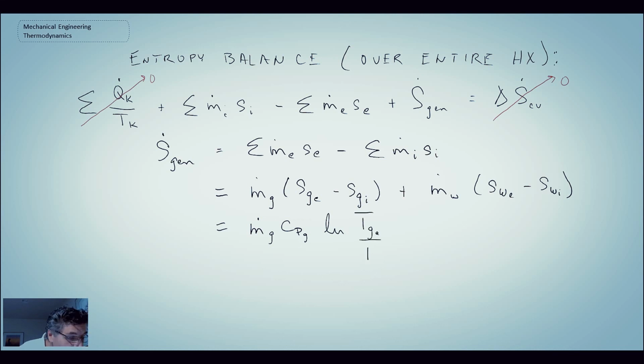And this is where you would want to ensure that your temperatures were in degrees Kelvin. The other place would have been had we had heat exchange and we had to use the first term in the entropy balance equation. This one up here, we don't need that though, but we do need it when we're evaluating the change in entropy of either of the fluid streams.